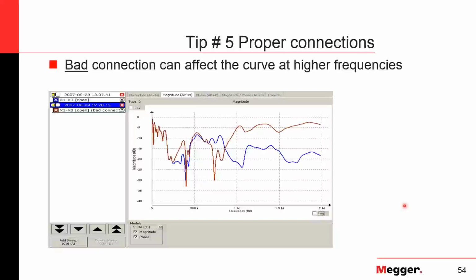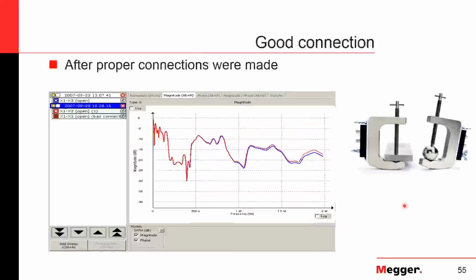And from this, I've seen some people actually go through and measure the termination impedance there to verify their connection. So continuing with connections, not only are you solid connected to the terminal where you're injecting and measuring, you also need to ground off these devices. And so we isolate, because it's that coax cable, you want to isolate and ground off this connection as well.